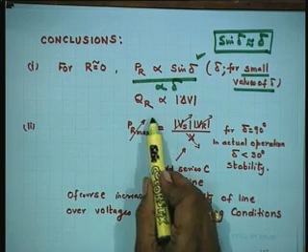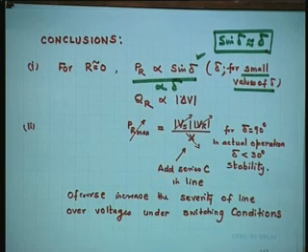And QR becomes directly proportional to the deviation, because other things are constant there also. The other things are VR and X. VR is also a known constant. That is what your job is, to keep it constant. If it is not, that is why you spend a lot of money on UPS and voltage stabilizers. For anything you purchase in India, you need a voltage stabilizer to stabilize the voltage to a constant quantity.